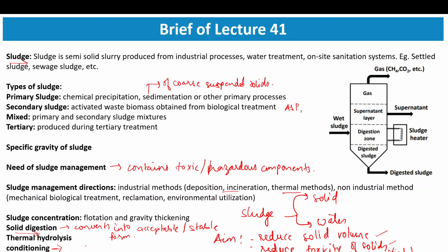So here we neutralize the charge of the solids or the sludge, and by doing that we increase its weight, or allow them to grow and form bigger flocks, which are easier to settle. So bigger flocks form, and hence they are easier to separate.